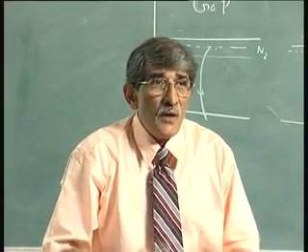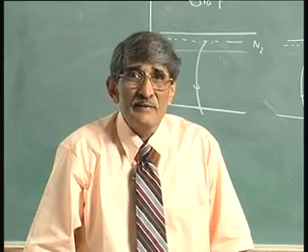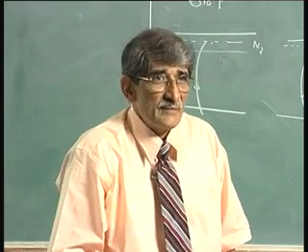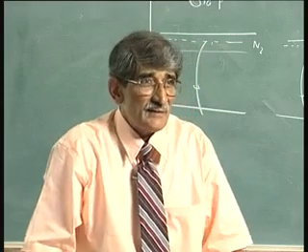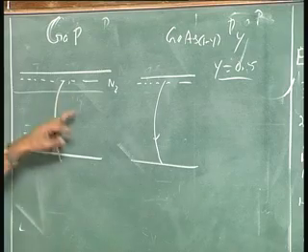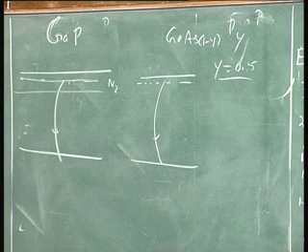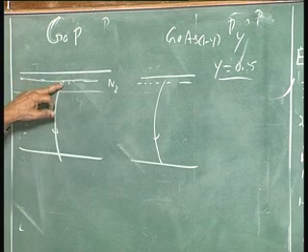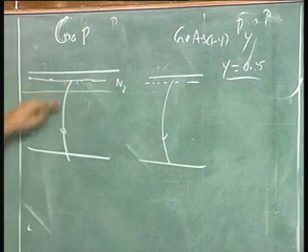But now, how good is the light, how much light is emitted for that particular wavelength depends upon how many impurities are present there. There may be unwanted impurities. Now, if you have unwanted impurities, I have put 2 levels here. When you put this level, if you want green light, you must have only the nitrogen impurity, because of that wavelength.